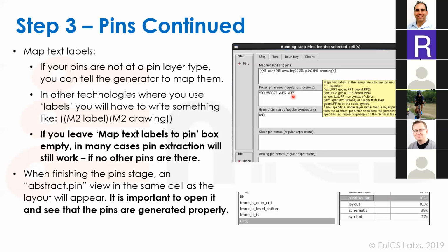But actually, if somebody has some flat design, like a medium design, he will do it and everything will be exposed. Yeah, doing it on flatten is a problem. Because if I just add the M5 pins without the drawing beneath it, then nothing is really generated and we can't really connect to these pins. So I have to add the metal below it. And if we do flatten, it will look for all the drawings inside. Yeah, it'll be a problem. I'm not sure how we can solve this.